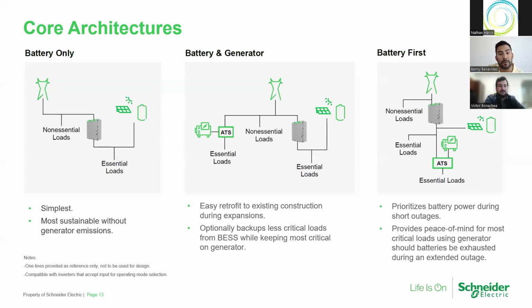When you lose power, these inverters can change state almost instantaneously. We're dealing with electronics here. So when you lose power, you could isolate, or SourcePack will isolate from the utility main. That inverter can change state almost instantaneously, grid tied to grid forming, energizing that utility main switchboard. Downstream you have these ATSs, and they will stay connected to source one.